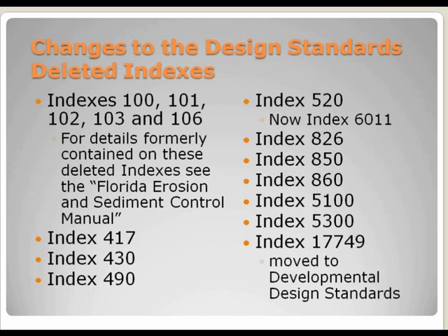These are the design standards that have been deleted. Indexes 100, 101, 102, 103, and 106. For these indexes, you need to be looking at the Florida Erosion and Sediment Control Manual now. They are no longer design standards. Some of the others were Index 417, Index 490, Index 520, which has been moved into Index 6011, and also Index 17749 has moved to the Developmental Design Standards, and I'll also show you how to find that.